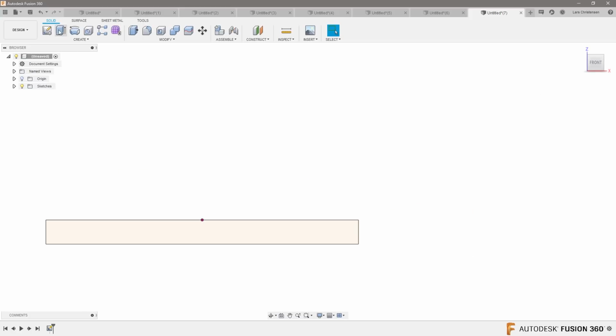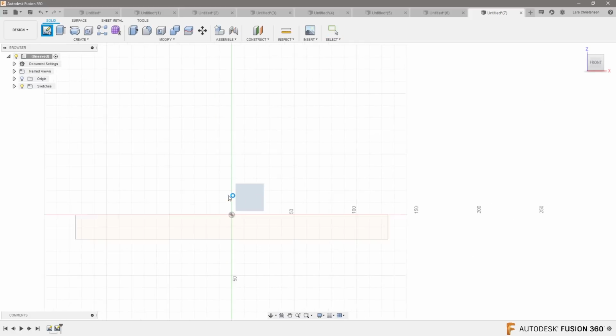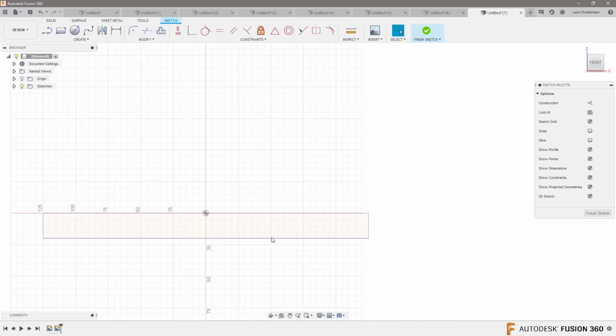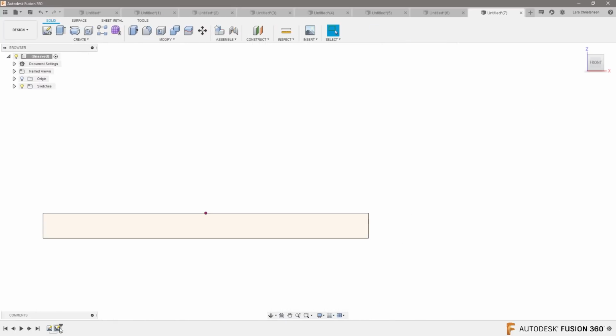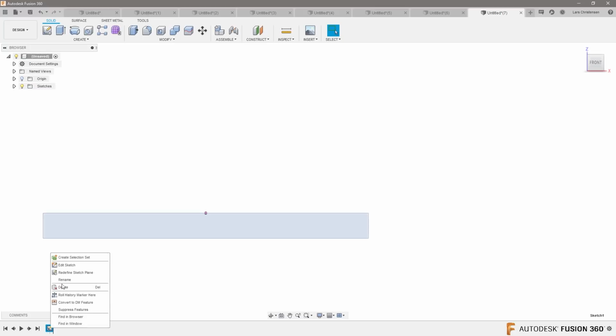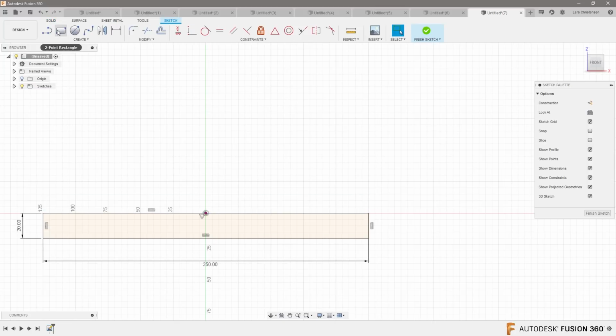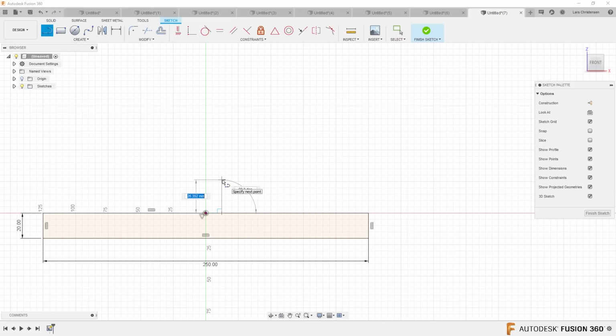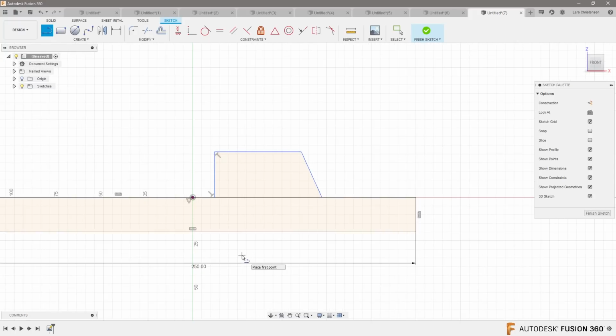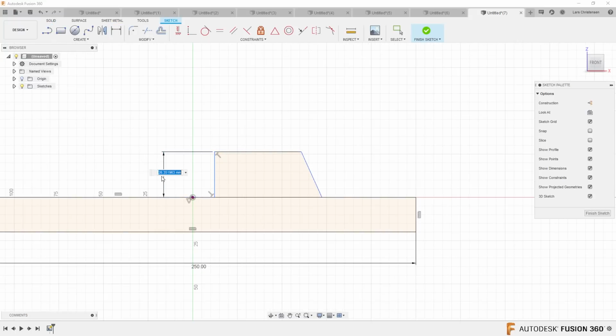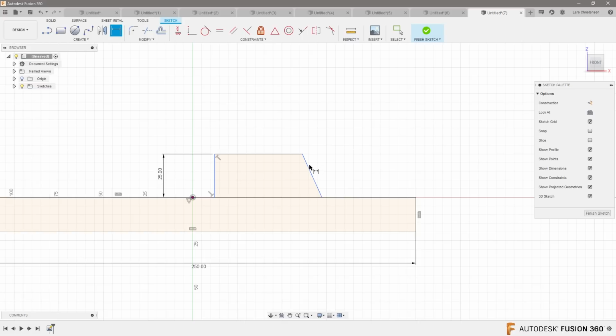Let's draw up an insert. I'm going to open up a new sketch on here. This could actually all be done in the same sketch. Let's do it all in one sketch. Edit the first sketch. So there's a bottom mold plate. I'm going to draw up my slider from the side view. So here's the slider going over. It's going to have an angle kind of going down like that. And let's just put some dimensions on it, Brian. I'm going to make this 25.